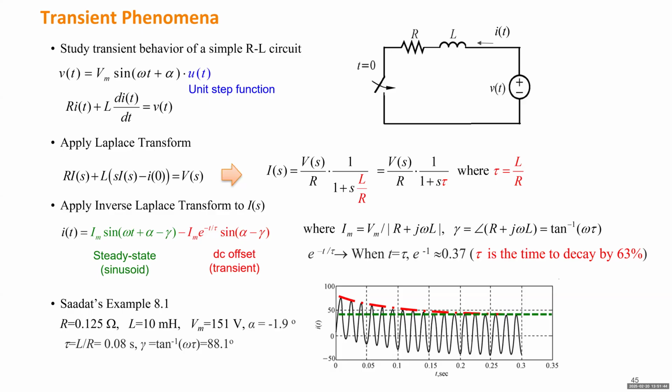So if you have a very fast dynamic, which means the time constant is very small, then we need to know which L and which R will cause this tau. Like for sub-transient dynamic, let's say the tau is 0.01 or less than 0.1, we need to figure out which L and which R will create this tau. And those L's or R's correspond to the branches, the part of the circuit, which really characterize the dynamic of that time frame. Then you can ignore anything else. That largely simplifies the circuit.